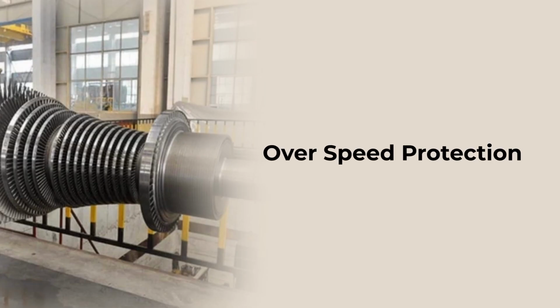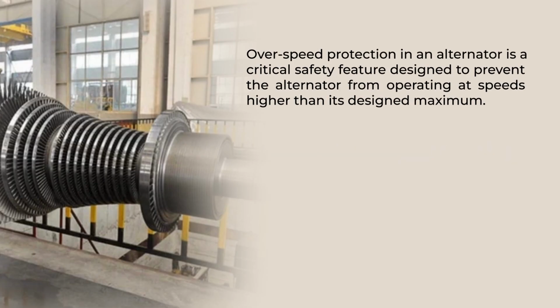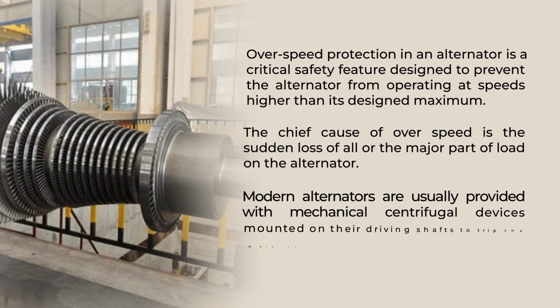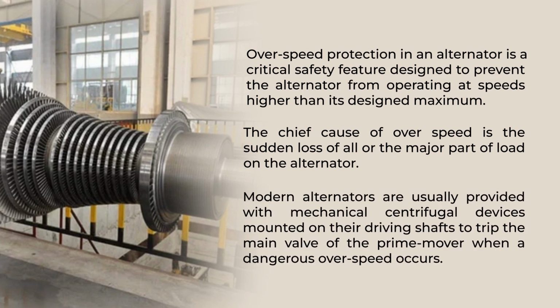Next one is the overspeed protection. Overspeed protection in an alternator is a critical safety feature designed to prevent the alternator from operating at a speed higher than the design maximum. The chief cause of overspeed is the sudden loss of all or a major part of the load on the alternator. Modern alternators are usually provided with a mechanical centrifugal device mounted on their driving shaft to trip the main valve of the prime mover when dangerous overspeed occurs.